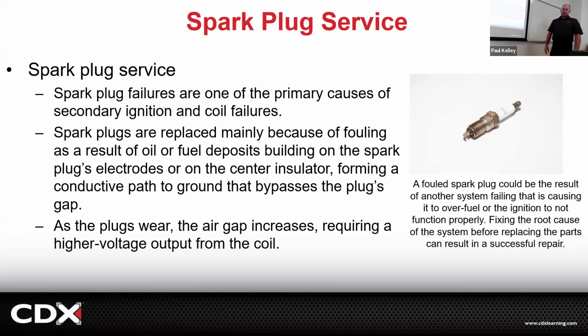And that makes it so that the spark plug will, like it says, it should build the spark and go through the center electrode through the insulator and then jump the gap, right? But if it's fouled, instead, the fouling will form a conductive path to ground. Well, think about what that means. Spark is like water. It takes the path of least resistance. Water is like college students. They take the path of least resistance.